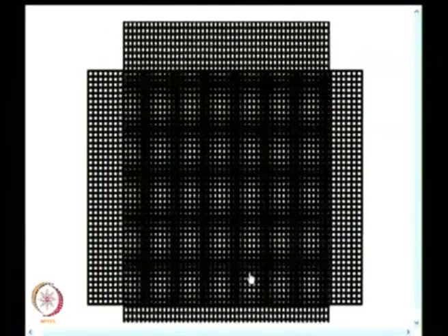You have to interpret horizontal fringes separately, because we have always seen, I have a grating, whatever the fringes perpendicular to the grating direction, you will find out: if the grating is aligned in the x direction you get the v displacement, if the grating is aligned in the y direction you get the u displacement. Here I have a cross grating, so I get u and v displacement simultaneously.